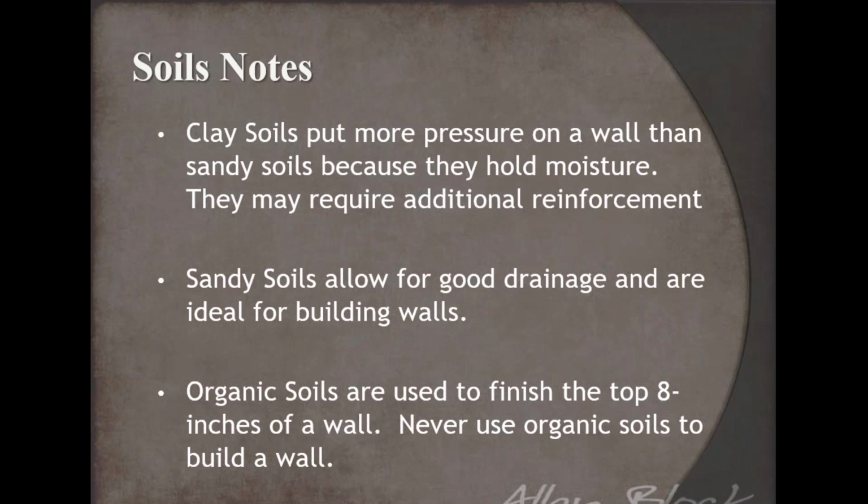And then we've got the organic materials. Obviously, the big red flag for organic material: we never use that in wall construction or really any kind of retaining wall construction for that matter. Great for restoration activities. We can stockpile that material and bring it back onto the top couple inches or millimeters of your wall for growing things, but we never use it for wall stability.